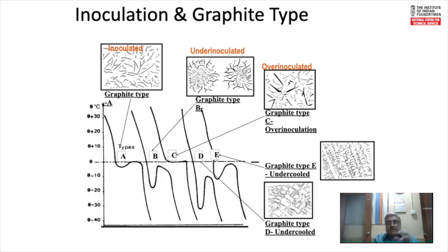Now you have austenites. You can see the dendrites here and the interdendritic liquid as it freezes, with randomly oriented small graphite flakes coming out. And type E, as we had discussed earlier, has a higher degree of undercooling, but oriented graphite flakes. This is undesirable.